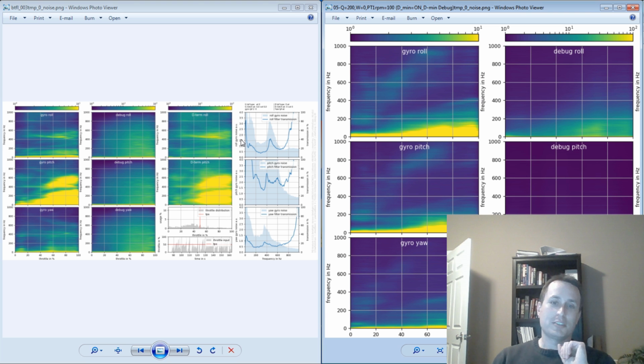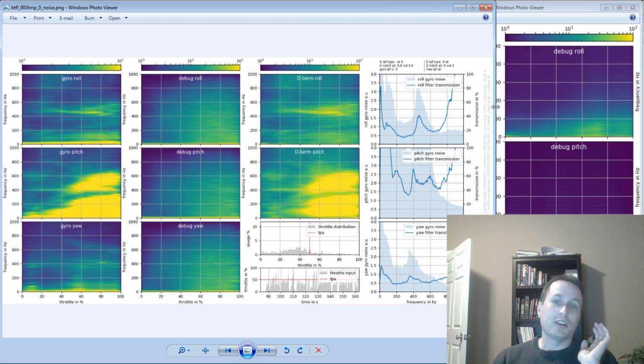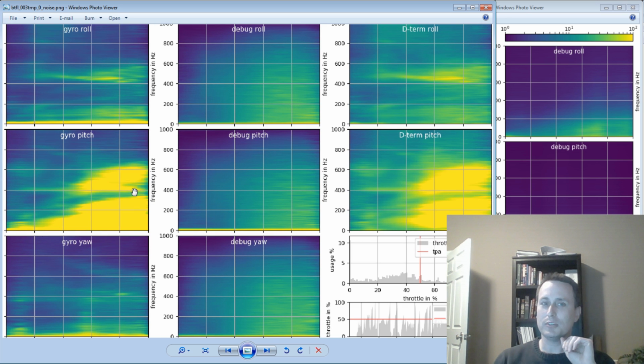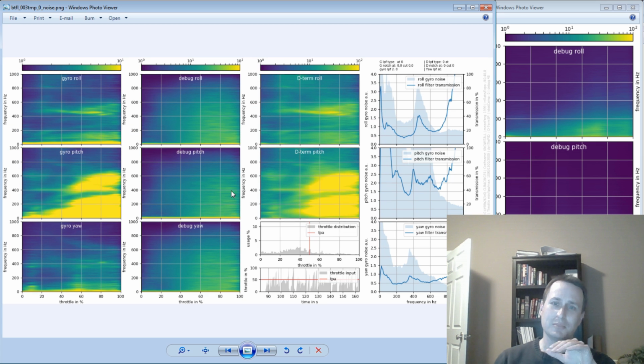I'm fully aware that Joshua Bardwell just did a video on this, and I don't think he was that impressed. He was gracious enough to upload his logs onto a group, and this is what his logs look like from that flight. So something wasn't right. It looks like the RPM notch filters were on. I believe he turned off the gyro low pass altogether, and then the D-term low pass altogether. That's a little aggressive. I wouldn't do that. You can't turn off the D-term low pass, and you can see his pitch axis is a mess. So that's what he was getting on that.